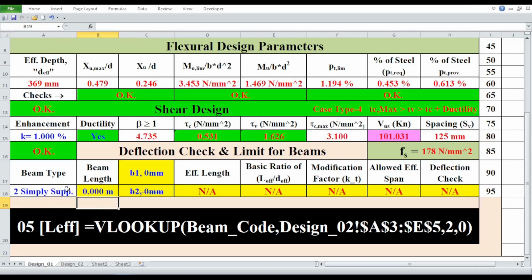Returning to 1 cantilever and entering 250 mm in cell C18, you'll notice the cell now has a yellow fill and the text 250 with a strike through, indicating it's not applicable in this scenario. Deleting the value in C18 removes the yellow fill. Now, with cantilever selected, let's set the length, L, to 4 and the first support width, B_1, to 250 mm.